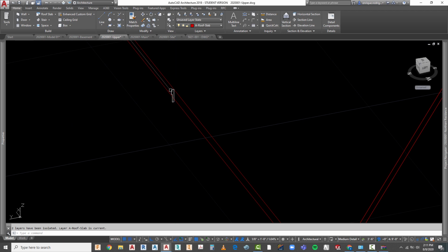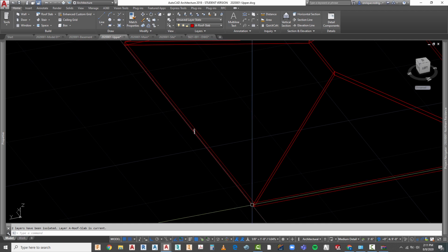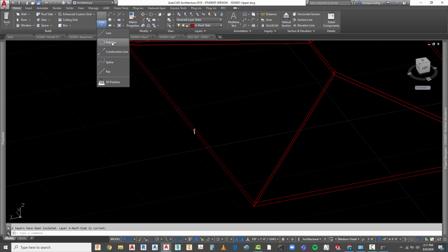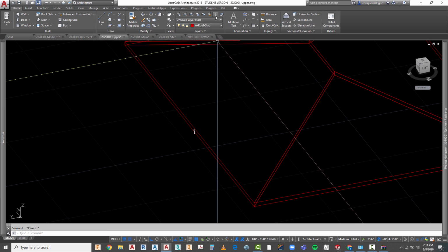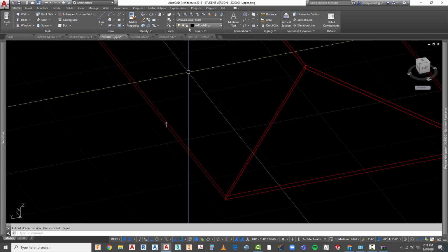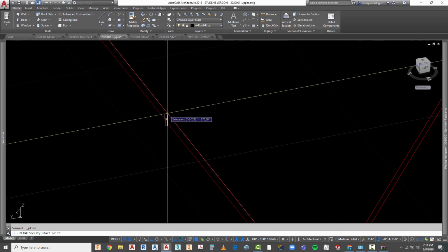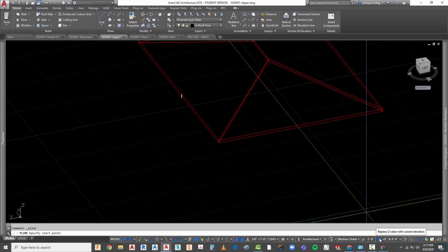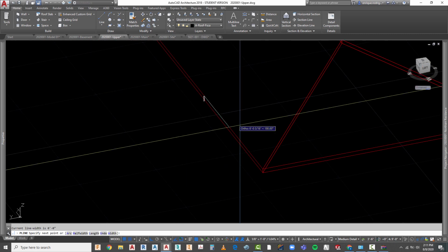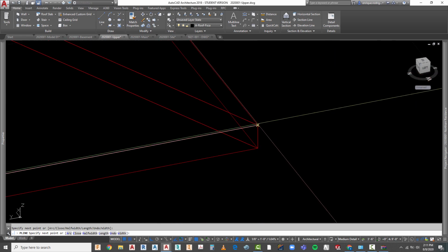Do not ever bring in a profile and start at a corner like this. It makes no sense at all. And the computer gets confused on exactly what they're able to do. Okay, I'm going to select polyline. First thing I'm going to do though is make this my current layer, a roof fascia. I'm going to start with polyline, start at this point. Once again, it's not letting me clip, so I need to take off temporarily my Z coordinate and click from that point to the top here, top there.